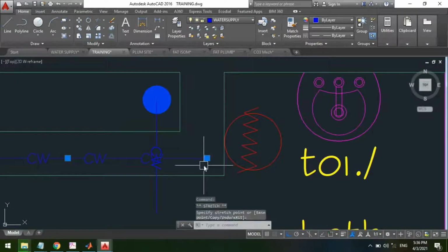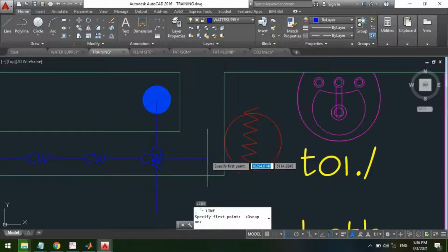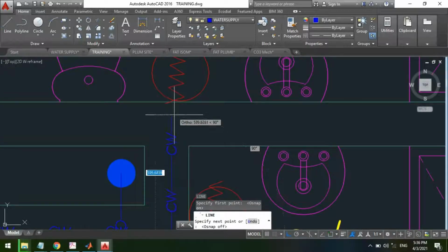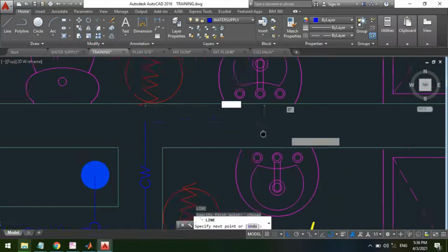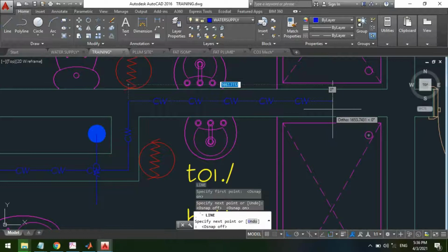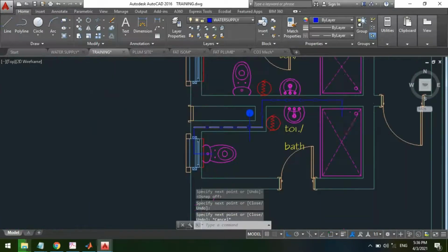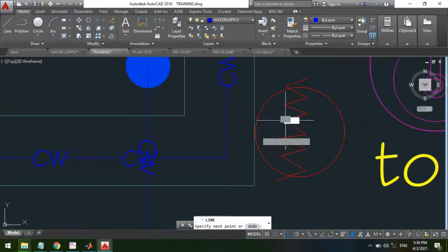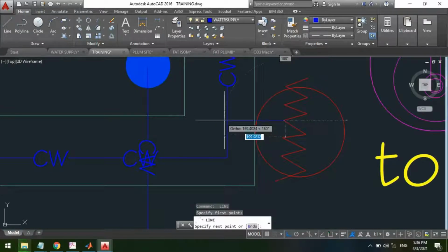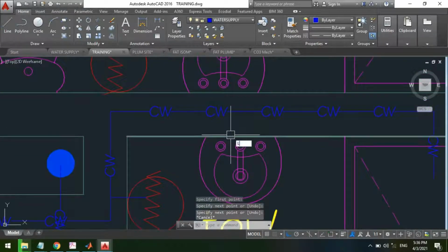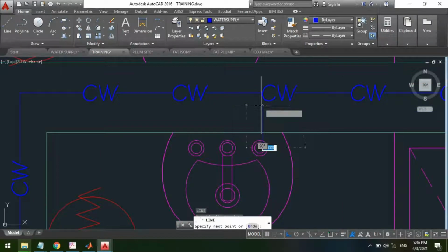while the same network will be extended towards the axis inside the wall. L enter again, F3. The network goes towards the axis and we terminate it here. So we link this to our storage tank, water heater, while we also link this other WHB.